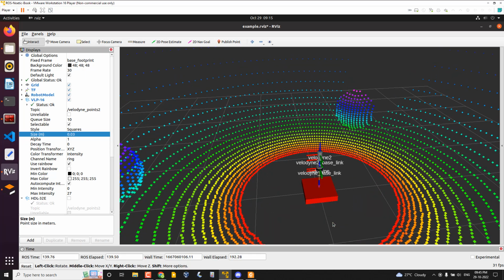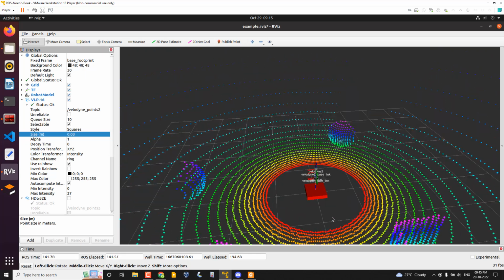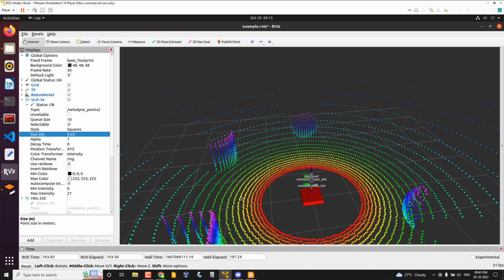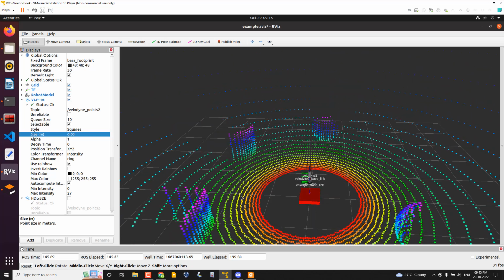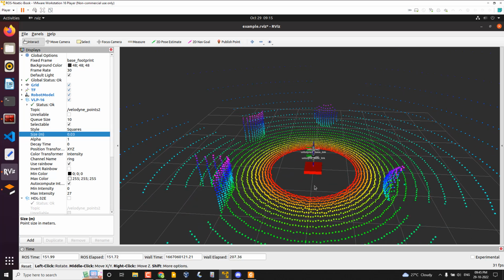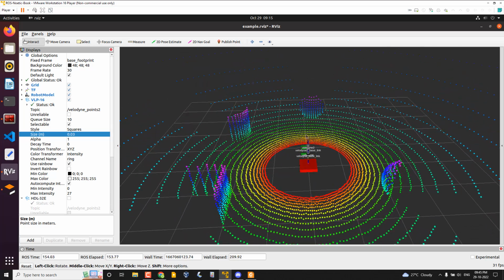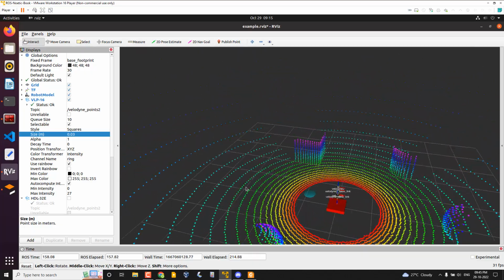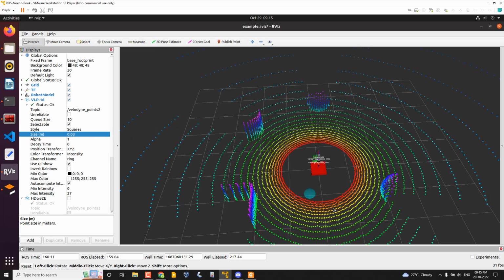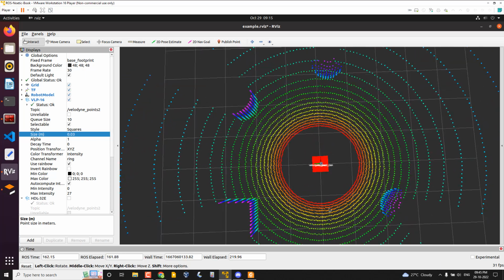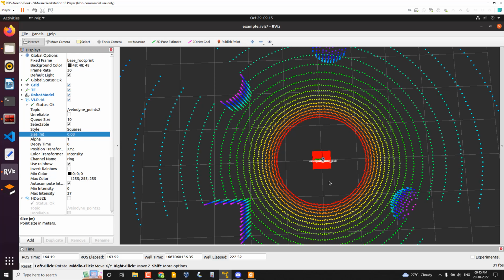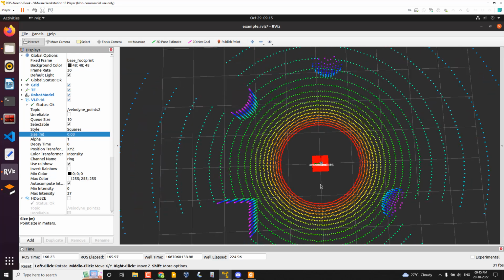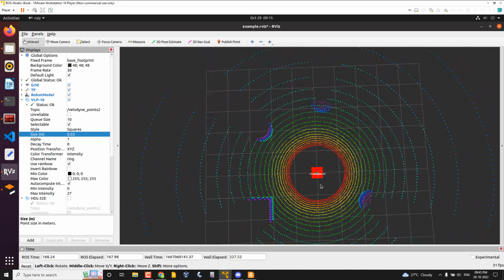We are trying to write some plugins on Gazebo. So first we will see some pure Gazebo plugin which doesn't have any ROS APIs. After that we will see how to write a basic plugin with a subscriber in Gazebo, with the ROS API. Okay, so this is actually the application. If you want to create a new sensor or any robotic mechanism, you can extend it by writing plugins.